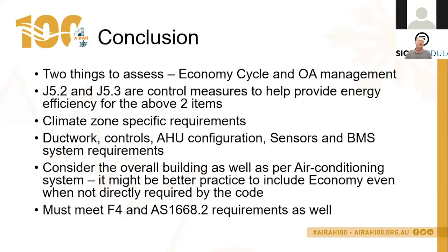If you're running a VAV system in economy mode, you'll have your outside air rate adjusting in accordance with the supply air requirements for the spaces based on your VAV control. You need to make sure your BMS system has those algorithms in place and adjusts control accordingly.